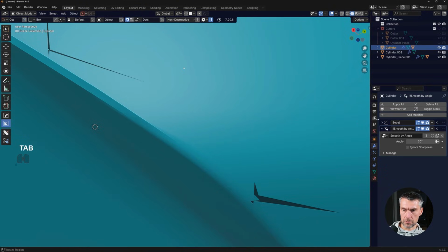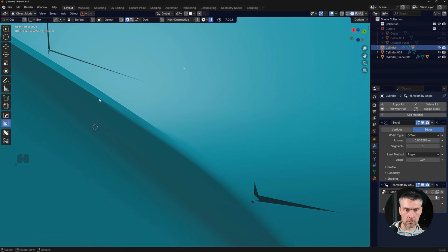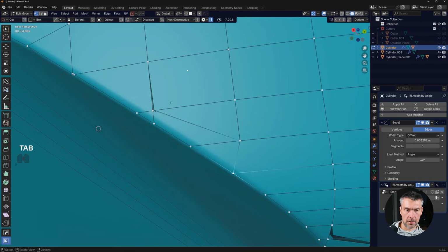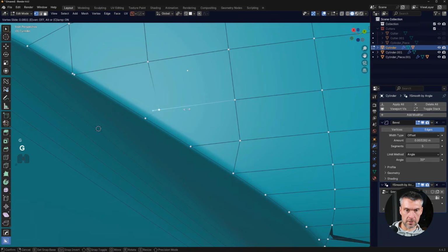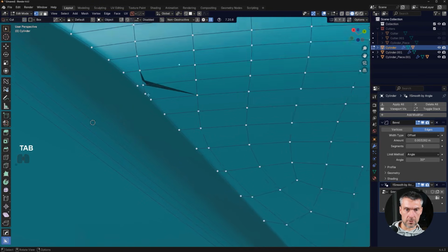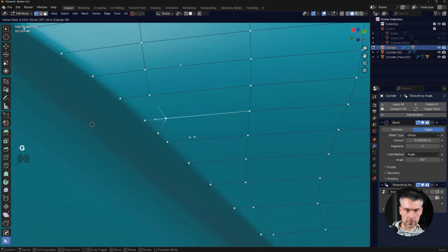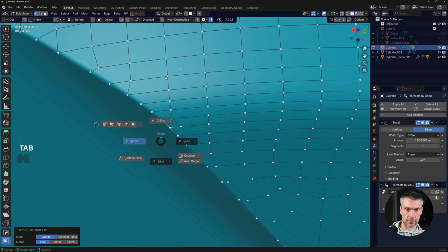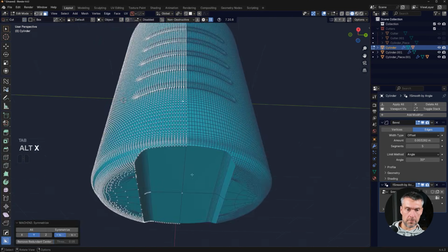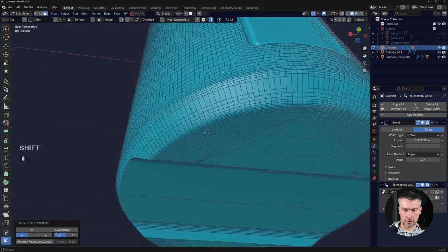This bevel should have more segments because we're losing the bevel here, so run it at 5. This one is interfering with the bevel, so combine these two and move this one slightly away from the structure. And this one too, move it in here and combine these two, you're peachy. Then simply mirror here, and you're done.